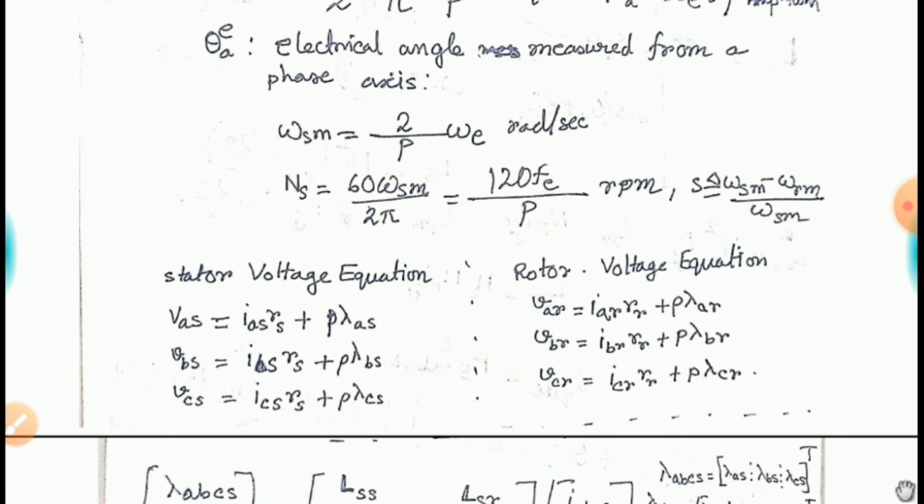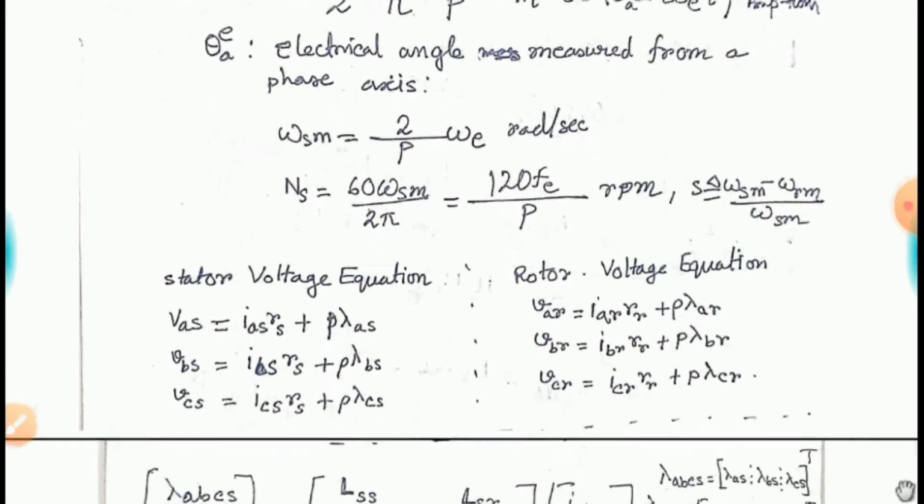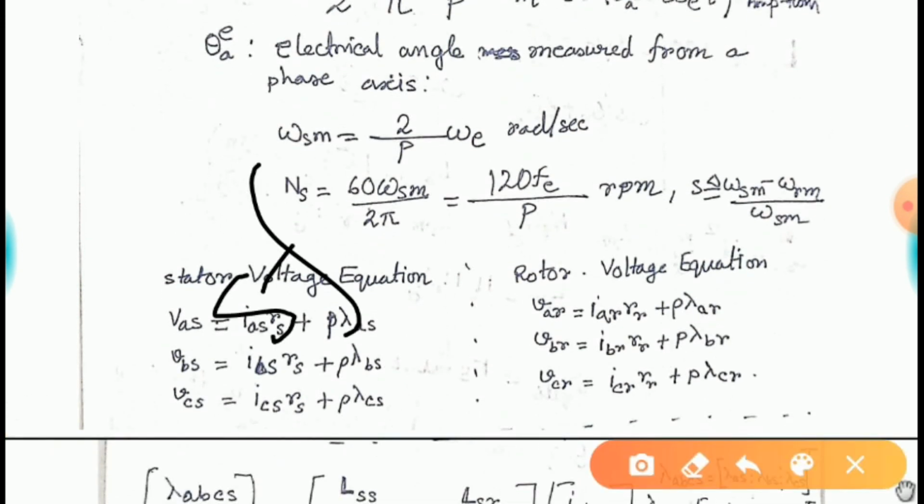This makes the whole system a bit fragile, and not that compact like the squirrel cage induction motor. So the one most promising feature of the slip ring induction motor is that you can have full control over your rotor resistance, and not only that, you can also control the voltage available across your rotor circuit terminals. We know that the rotor circuit voltage has a frequency SF, right?